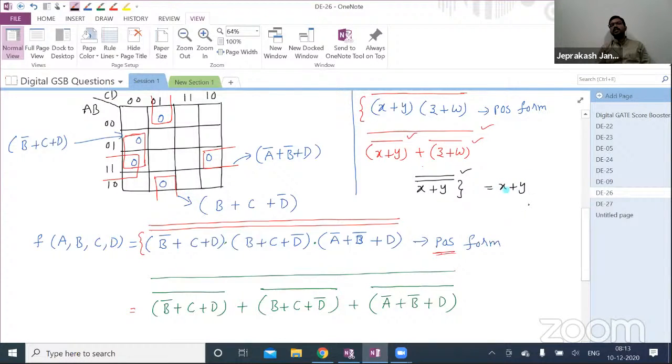This is the OR gate, or logical OR function. Since you are using a NOR gate, first you will get the NOR function. After that, you have to pass this output to one more NOR gate which has the same 2 inputs, like that. So like that, just observe. Here C plus D is there, right? So you apply 2 times complement. Clear? Right. Here B plus C is there. Apply 2 times complement.